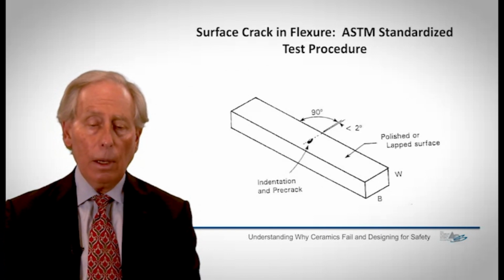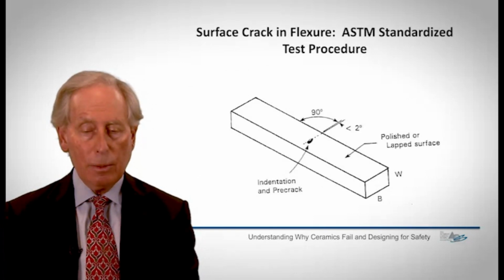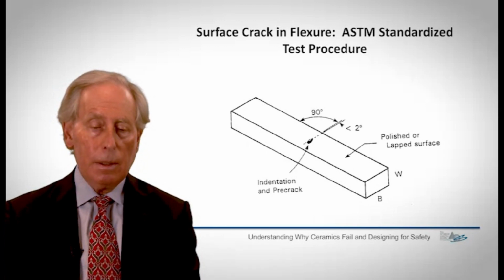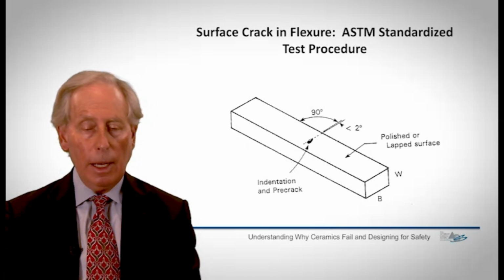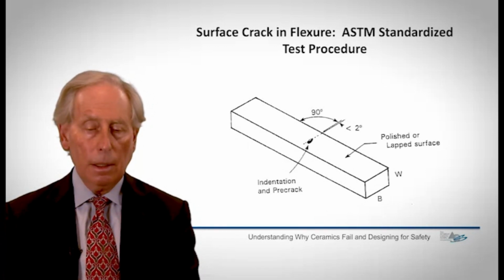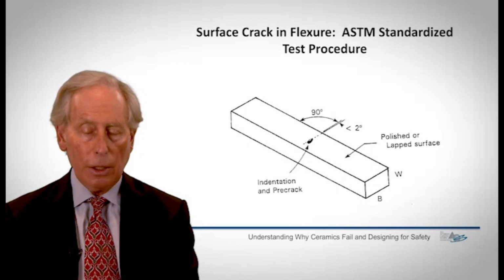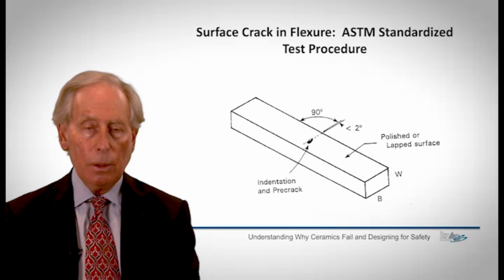There are several, though, ASTM standard test procedures, and I'll just briefly go through those. For instance, this is what is called a surface crack in flexure. At the end of this series of lectures, and this lecture in particular, I will give reference to all of these ASTM standards, and I strongly encourage that if you're going to conduct this test, you go to that and follow that procedure, and it gives you quite good data.